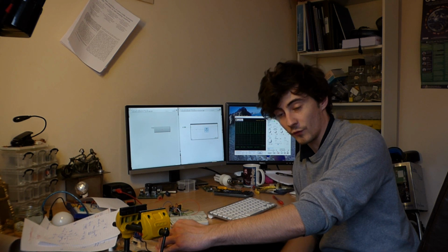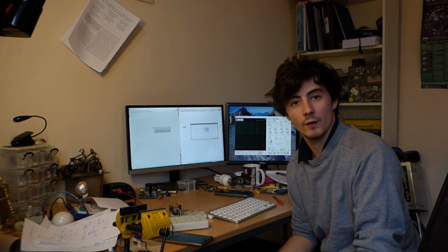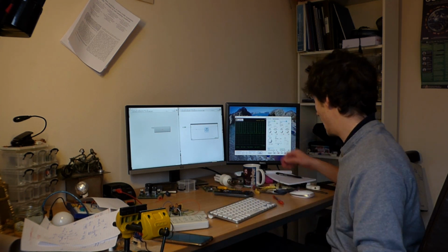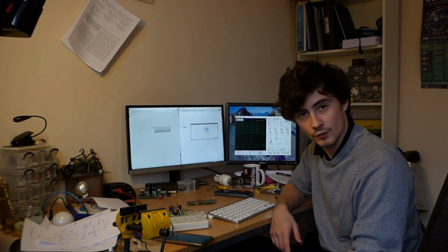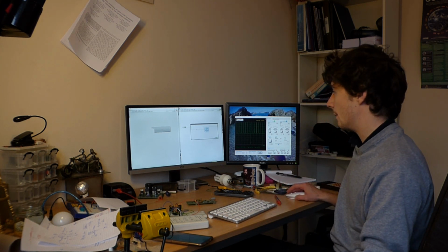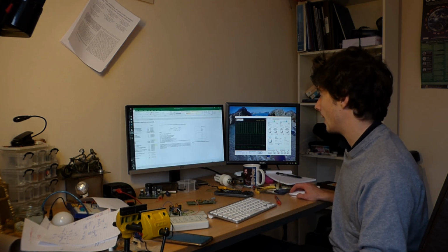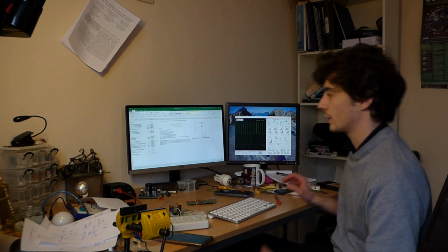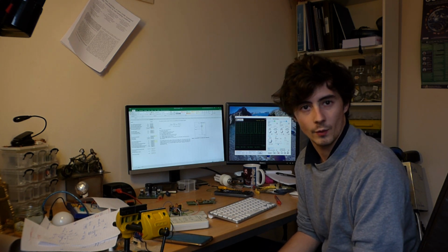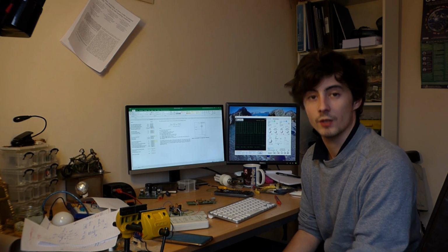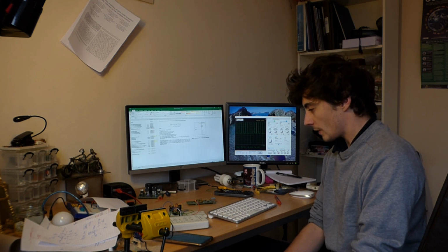Using the IR2110 is really simple. So if you've got any application where you need to drive a MOSFET or something like this, and the usual microcontroller just doesn't quite cut it, then have a look at the IR2110. Do the calculations yourself. Very simple. I've got some spreadsheets that I keep primarily for doing the calculations, otherwise I just have to type them in every time, by hand. Quite often I'll use the same MOSFETs if I've got some lying around, so generally the equations are the same, maybe just the switching frequency changes. So yeah, that's all there is to it.